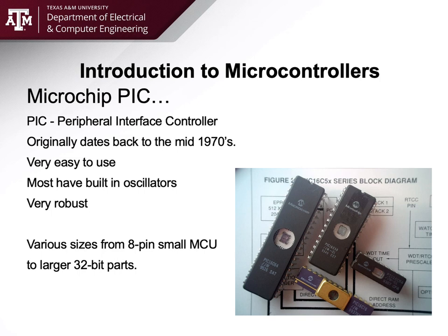You will notice this little quartz window. This actually is the die of the chip in the center, and there's a little quartz window. So this generation here, and I know these really well, this is how I cut my teeth doing a lot of embedded systems development 25 years ago. If you wrote code for these, you actually used a UV eraser, a UV lamp on your desktop, and you would actually put the chip over the lamp. I guess you could technically have gotten a nice little tan if you wanted to. So I actually had a UV lamp on my desk, and it would erase the contents of the